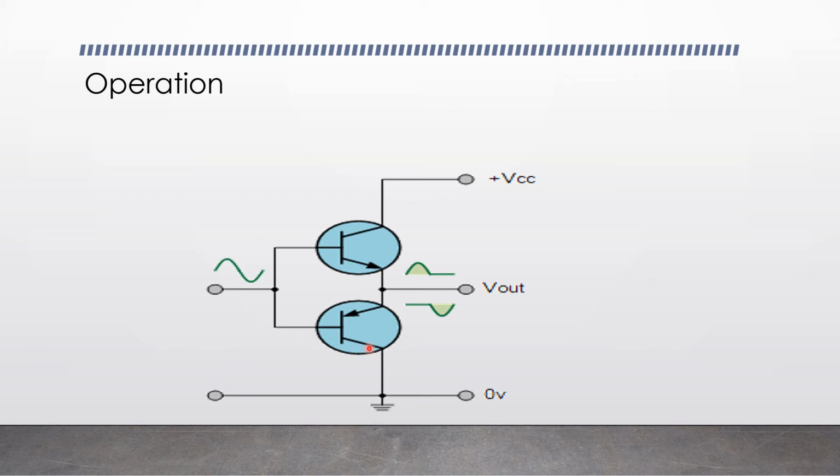So the transistor conducts only half of the time, either on the positive or negative half cycle of the input signal. And since no DC voltage is biased to the transistor, the output transistors need a base emitter voltage to start conducting each half of the waveform, both positive and negative.